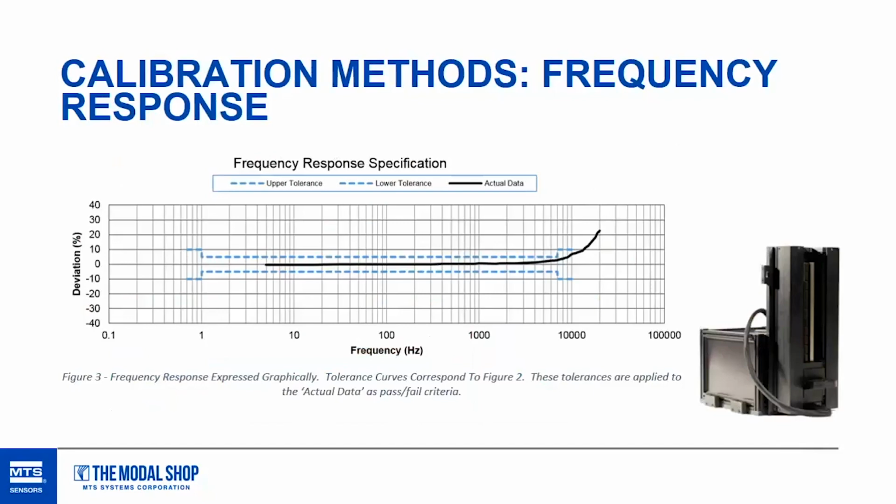If we wanted to go lower in frequency, we could use a shaker like on the right there, a low frequency shaker that has a much longer stroke to get more output out of the sensor, and test that sensor all the way down to 0.5 hertz, or 0.1 hertz in the case of an optical encoder based low frequency shaker there. So this, again, it's the tolerance bands that you'll be checking against. The low frequency is quite important for ICP in looking at what is the low frequency electrical characteristic of that sensor. How does it roll off due to those ICP electronics?